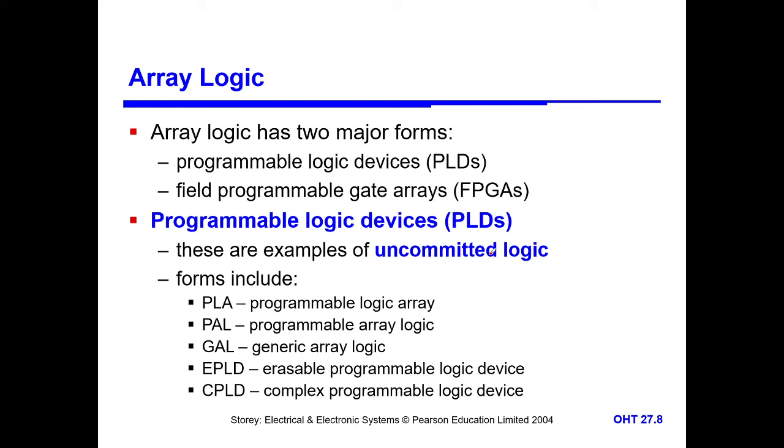Coming to the array logic, such as PLDs. PLD stands for programmable logic devices. These are the devices which can be programmed and which can function according to the program, and that program can be done by the programmer, that is a user only. Once the function for that program is done, we can erase that program so that we can write a new program.